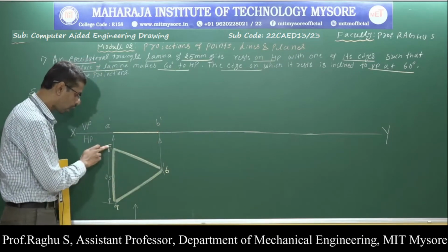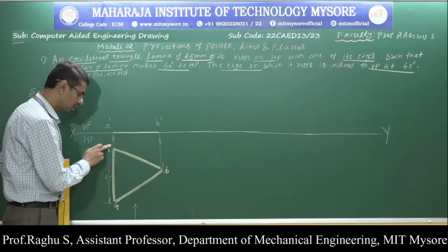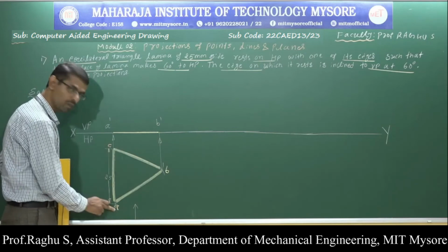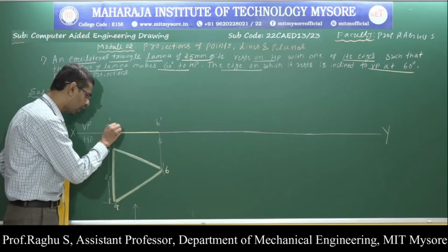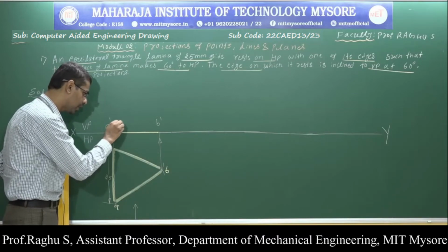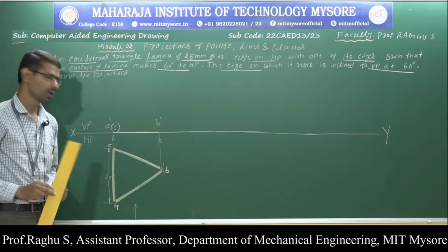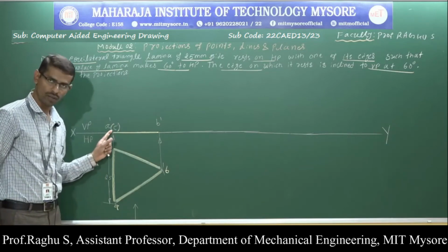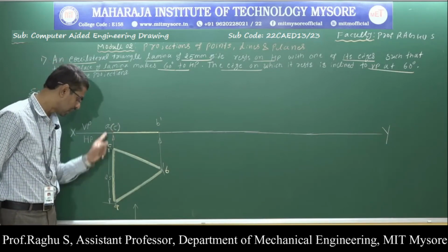And here I have point C just behind point A. C is invisible because it is just behind point A. Therefore, invisible corners are indicated in the bracket. Right. Front view naming. So A dash visible in the front view.